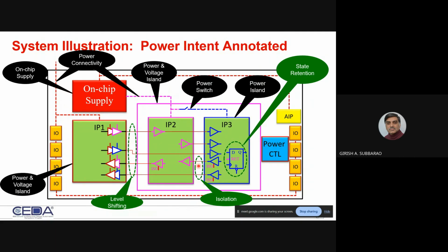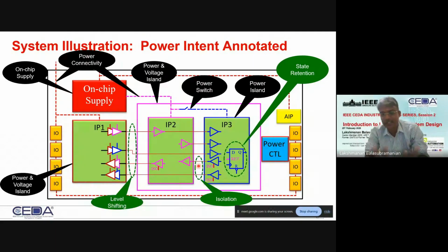Okay, fine. Thank you. Obviously we can go to the details of the isolation cell, how retention cells are designed. There we can look at the details, but at a gross level, resistors did the job earlier in custom integration of safe designs without reliability problems, with functional designs, without care for power, right? Once the low power requirements come, the resistors cannot do the job anymore. They are now dynamic kind of pull downs, as you see. Okay, thank you.